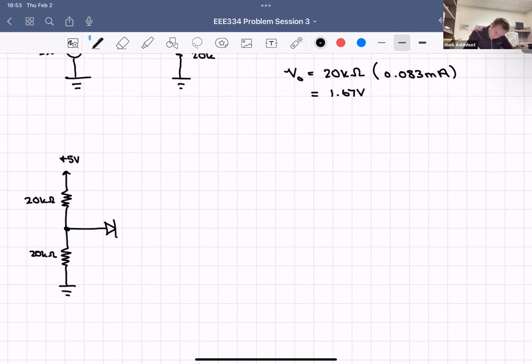We have a diode, anode, cathode. We have I. And then we have a load, 10K. Oh, I got mixed up looking at the other one. Sorry. This diode is going this way, and then we have, there we go, cathode, anode, left to right. Then we have our 10K that's going to ground. And then we have a 10K here going to a positive 3 volts.